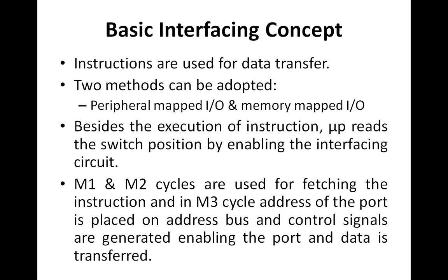Now in 8085, as I told you, in case of peripheral mapped input output, we use two instructions, IN and OUT. The IN instruction reads the data from the input device, and the OUT instruction writes the data into the output device. Both these operations, reading as well as writing of the data, are done with reference to the microprocessor's accumulator.